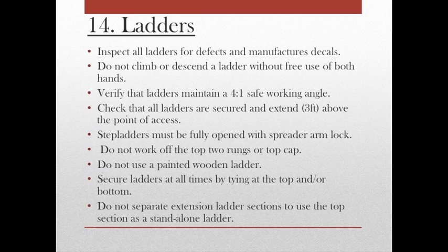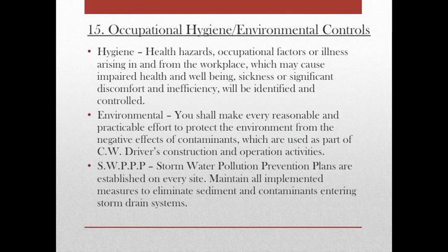Step ladders must be fully open with the spreader arms locked. Do not fold the step ladder together and lean against walls, columns, etc. Do not work off the top 2 rungs or top cap of the step ladder. Do not use a painted wood ladder. Secure ladders at all times by tying at the top and or bottom. Do not separate extension ladder sections to use the top section as a standalone ladder.